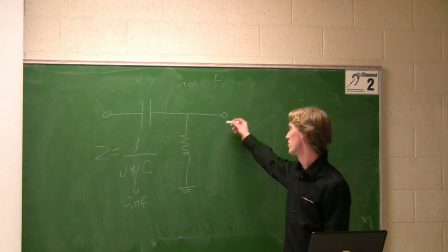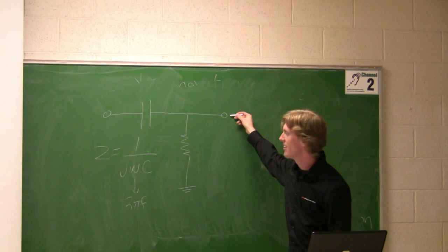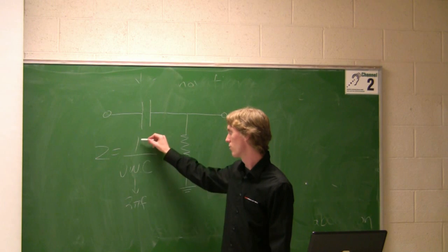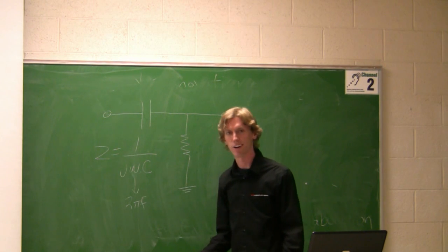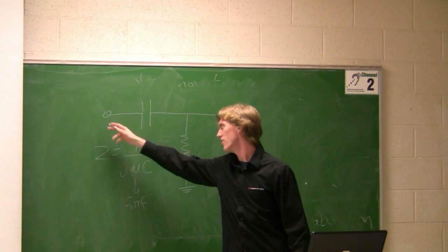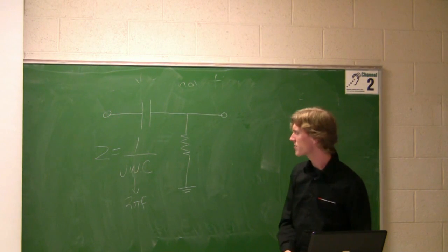So what is your output voltage going to be at low frequencies? Small. Basically nothing, right? On the other hand, say omega is very, very big, so you have 1 over a big number, then your impedance is going to be small, right? So it's pretty much a short circuit. Everything that's here is getting to here, and it passes without any restriction.